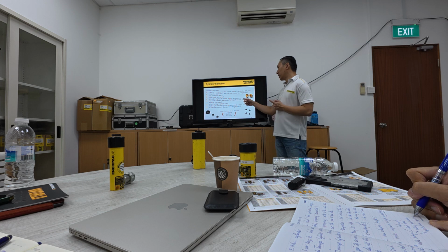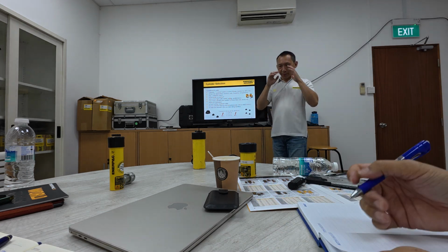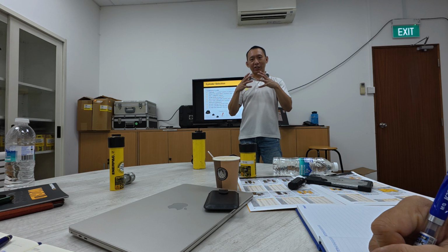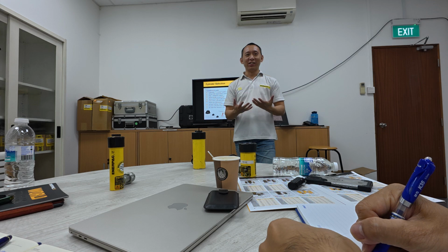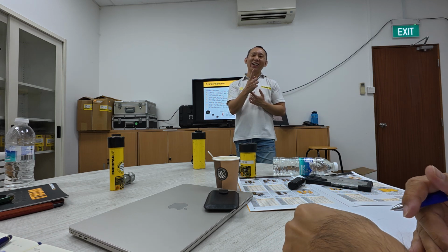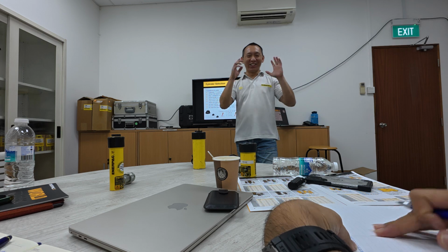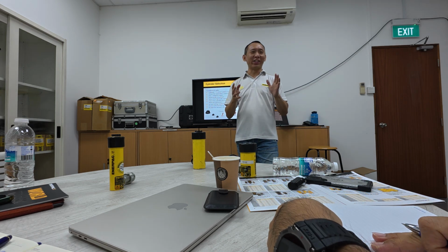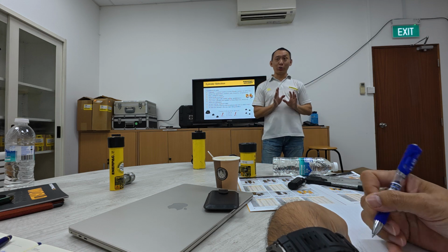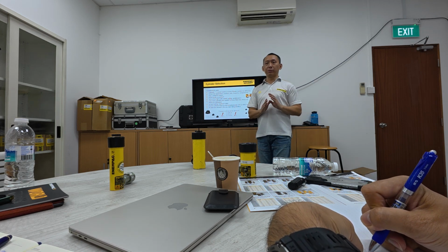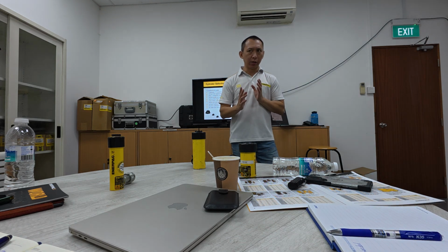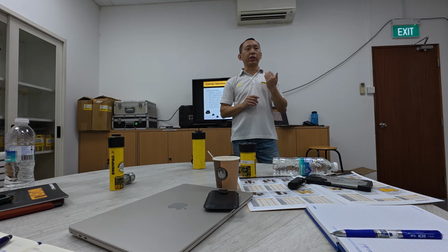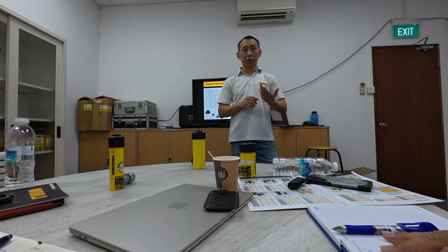Okay, how many cylinders are needed? Every time a customer comes to you to buy a cylinder, we always assume they just buy one. One pump, one cylinder. Very common, because we always have this mentality. But it's not always true. Sometimes the customer will need to do a lifting application, where we need more than one cylinder, or maybe two cylinders in pair to clamp or something. So it's always good practice to ask how many cylinders the customer needs.